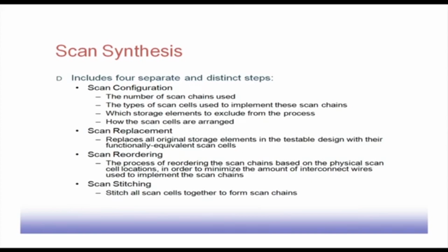Then the scan replacement will replace all storage elements in the testable design with their functionally equivalent scan cells. Once we have decided to modify some of the storage elements to scan cells, the scan replacement process will modify all those storage elements to the scan versions.